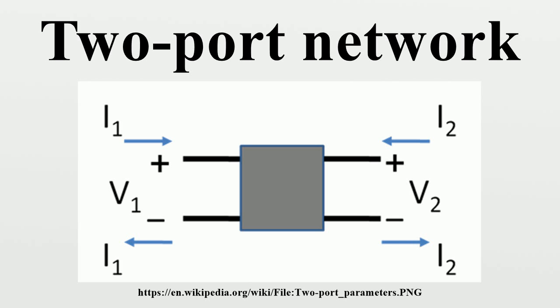Combinations of two-port networks. When two or more two-port networks are connected, the two-port parameters of the combined network can be found by performing matrix algebra on the matrices of parameters for the component two ports. The matrix operation can be made particularly simple with an appropriate choice of two-port parameters to match the form of connection of the two ports. For instance, the Z parameters are best for series-connected ports. The combination rules need to be applied with care. Some connections result in the port condition being invalidated and the combination rule will no longer apply.